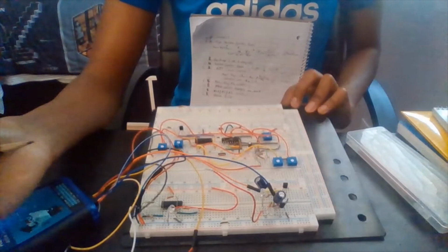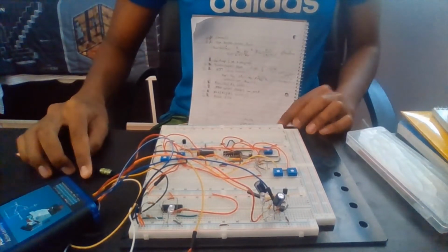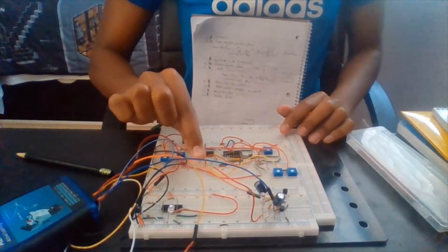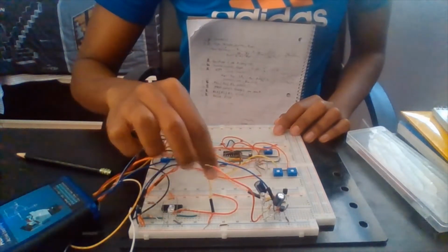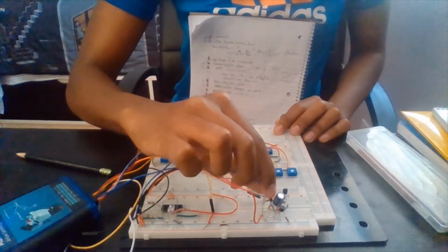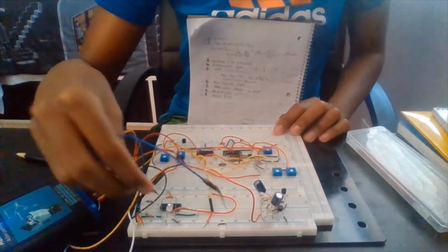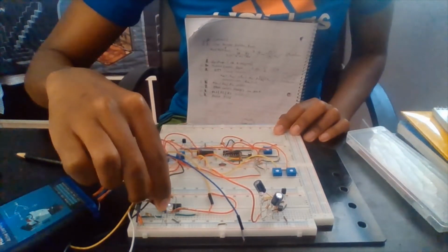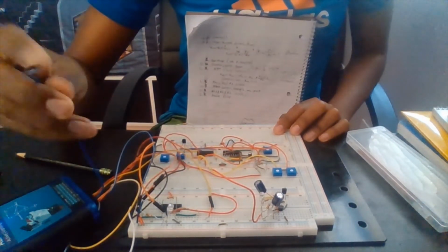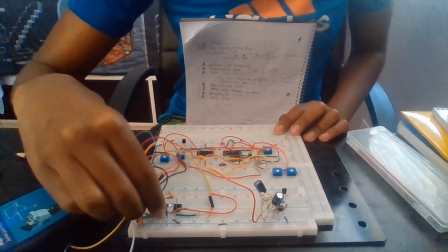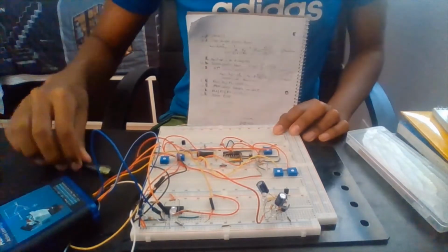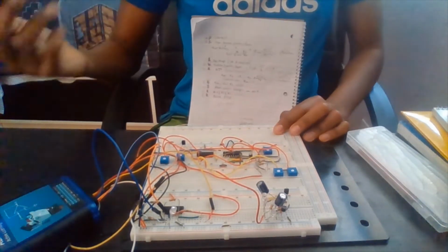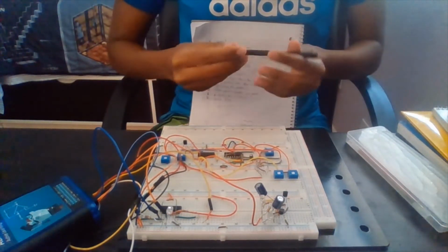I already gave you a rundown, but now to test it, let's go over here and get our channel 1, channel 2. Let's put channel 1 into the node with the LED, and then channel 2 at the first output of this operational amplifier, and this should give us an amplified version. So now we'll be moving over to Scopy.